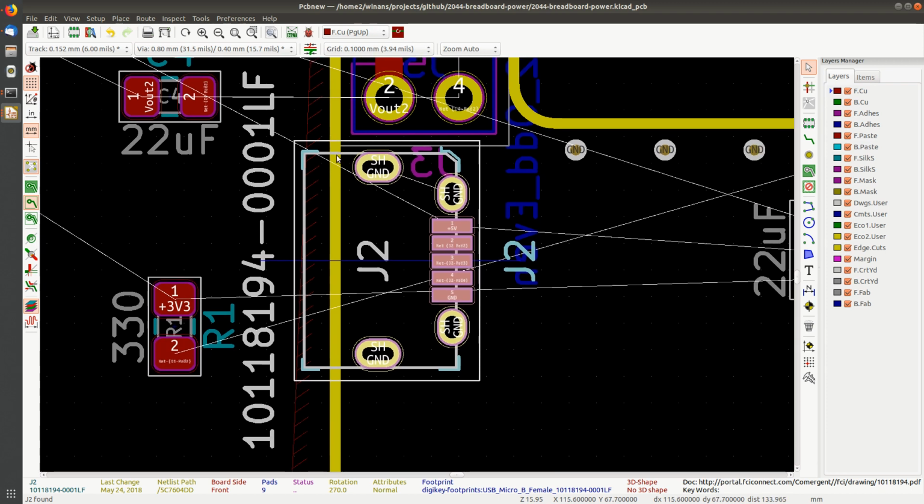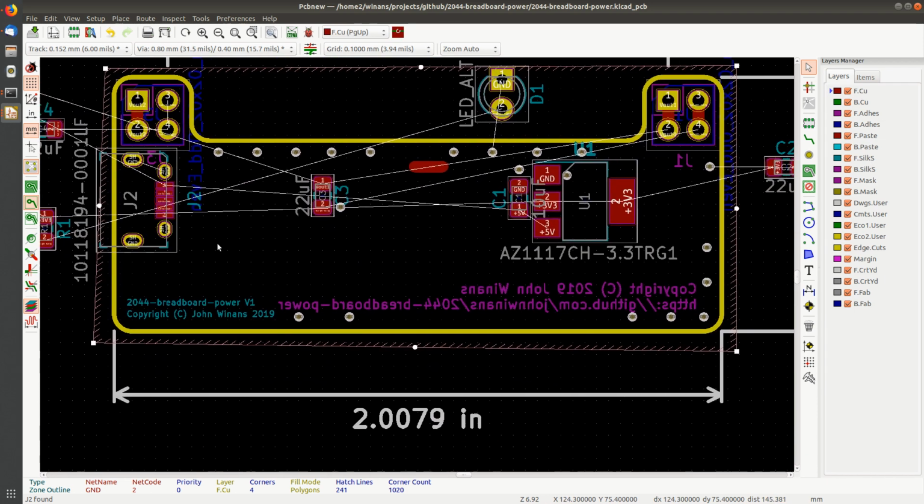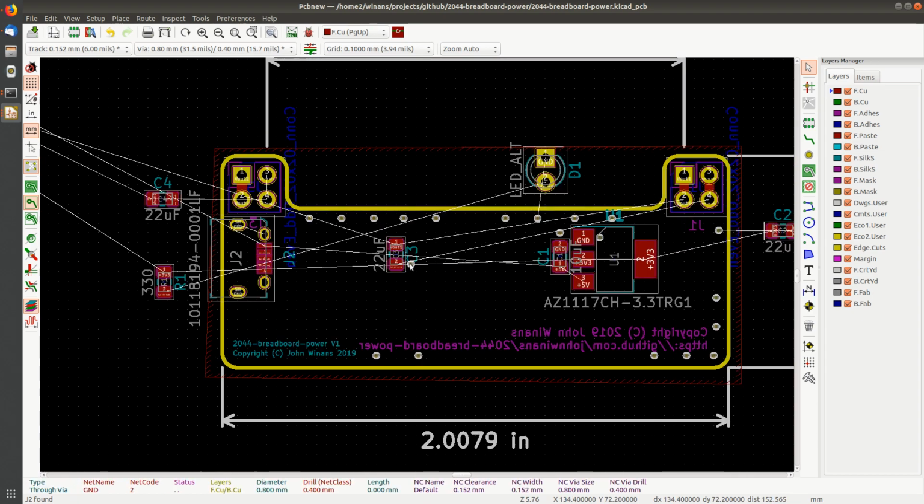It would have been nice if they put on the fab layer, which is this gray line here. If you click on fab, this just comes to the front. It would be nice on the fab layer if they put a line in their part. I could add it if I felt like it, but if I did that, I'd be modifying the DigiKey library, my copy of it anyway, and that's fine. I can go ahead and use it, or I can make a copy of this and put it in my library, whatever I wanted to do. If I use these a lot, I would do that, and I probably will when I get to the episode on how to make and edit your own part libraries.